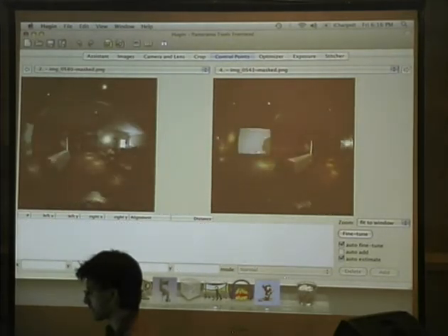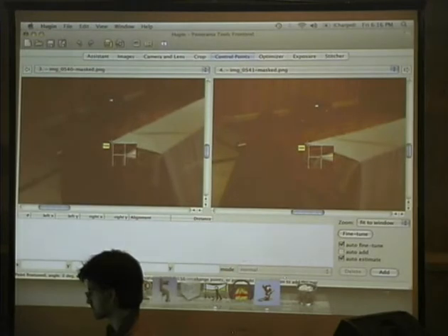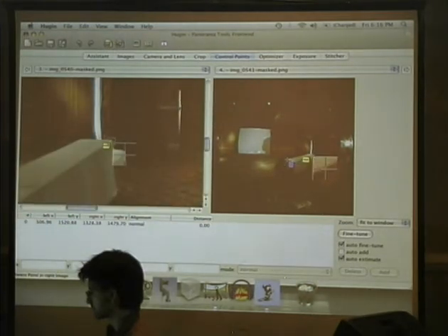Yeah, so if we were going to do multiple scans in this room, generally we imagine a 10-foot by 10-foot grid. 10 feet's pretty good distance. It really depends on the ceiling height. Actually, the more wide open the space is, the fewer scans you have to do. And the Panda scan is actually really great for that.